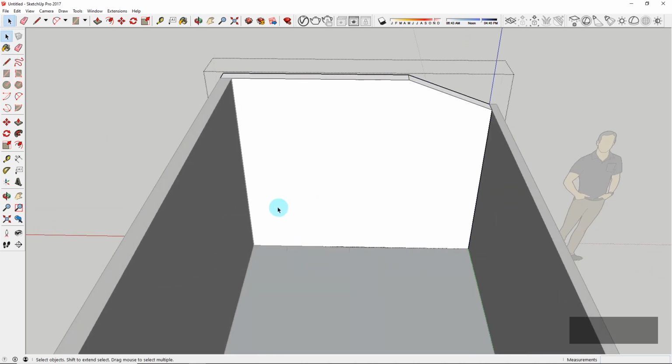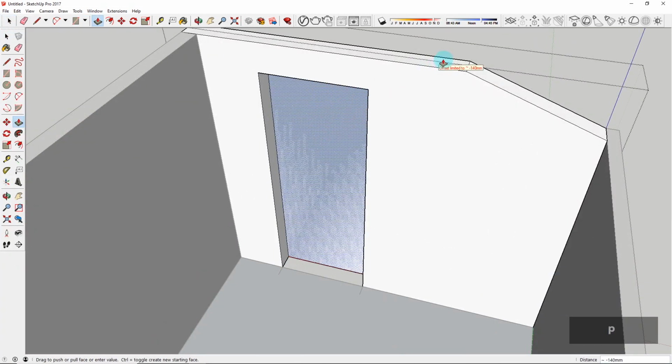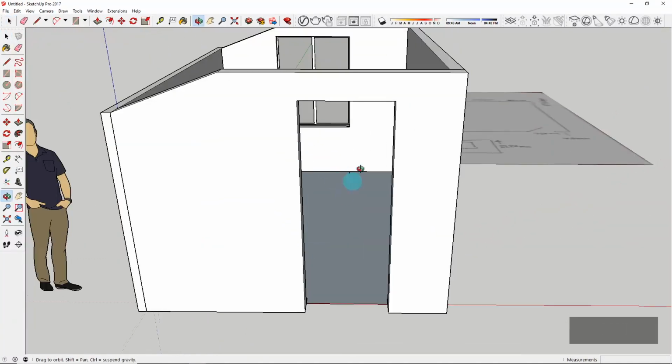So to do that, I'm just going to go into our wall section, and again, like our window, we will draw a rectangle, and that's actually locked on for me quite nicely. And I know my door is 2 meters high, so if you see in the bottom right, I can kind of do it by eye. Okay, maybe not. Let me just do 2000 by 750. Hit enter, and that's our frame. And then I'm just going to drag this through like before. So now we have an opening to the bathroom like that.